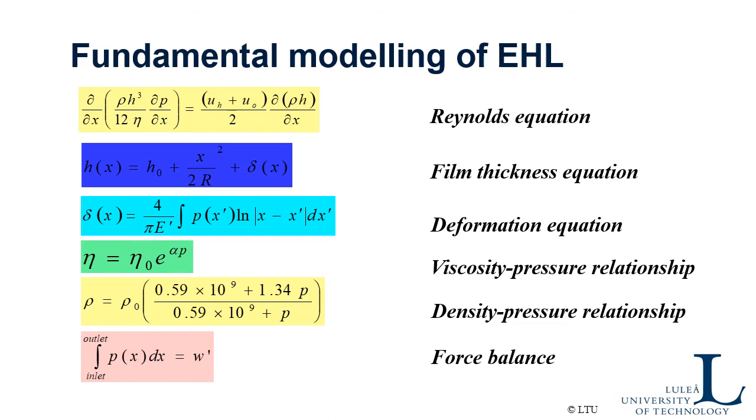That means the surfaces are deformed. The deformation is given by this expression, and look here now, in order to compute the deformation we need the pressure, but in order to compute the pressure we need the film thickness and the deformation. So this is a non-linear problem.